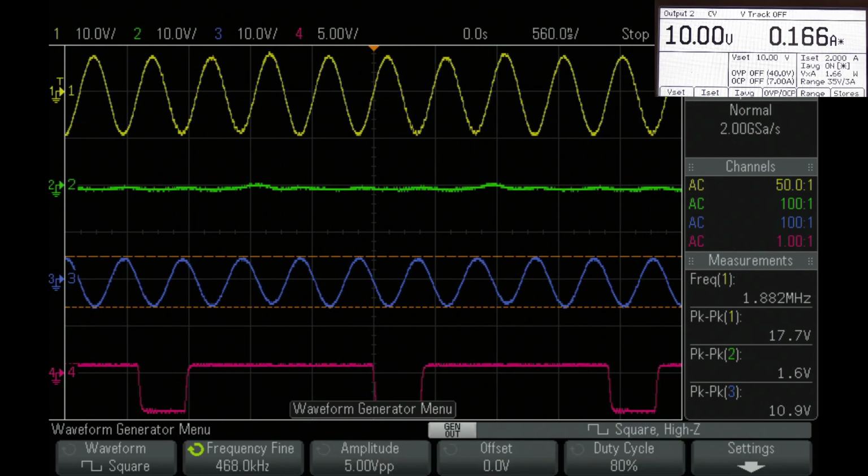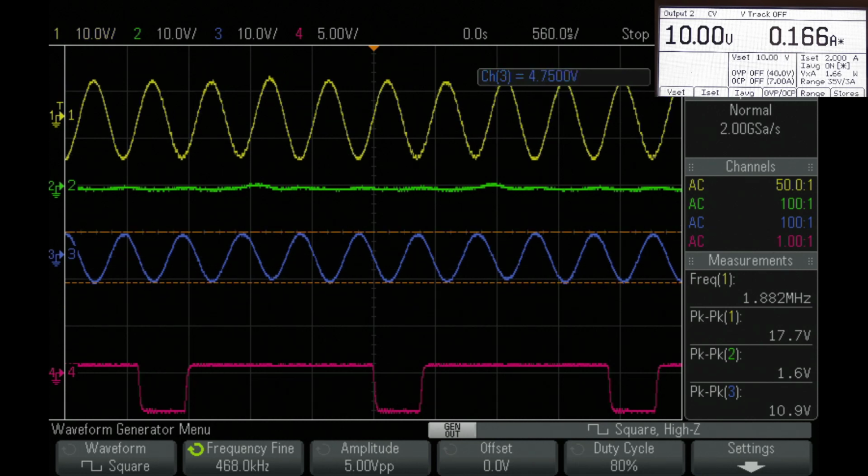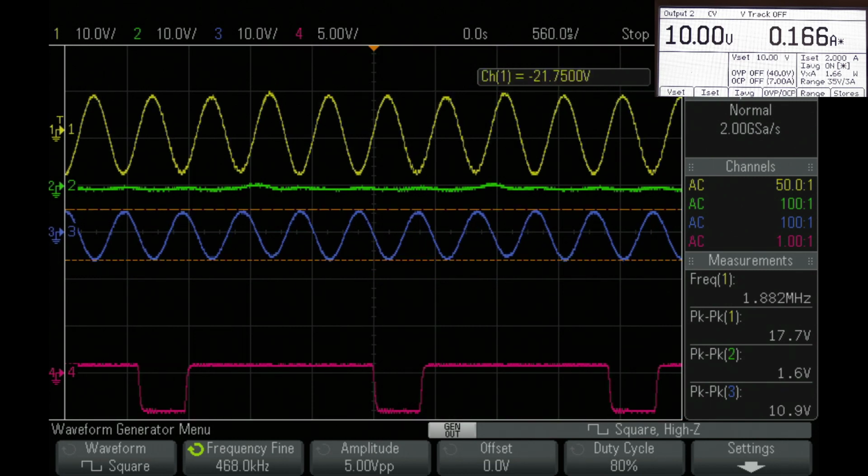So I stop that for a second and bring them both together. Very important here, I use an inverted signal. There's no specific reason for that, but when you look at the duty cycle, you see 80%, which is the opposite of a non-inverted signal. So technically I have the lowest trigger signal, like 20% non-inverted. As you can see, I use one signal to excite technically 4 waves. If you put them close together, you can see they're opposite in direction, and we have 0 in the center. This is a wave characteristic of an unterminated coil.